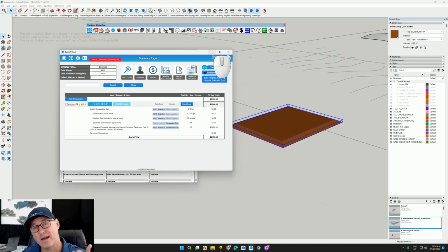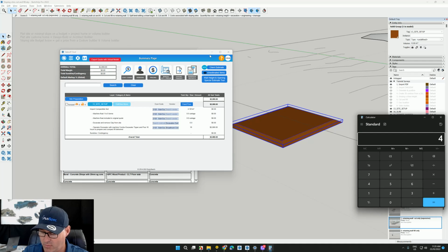Now, one thing about when you import fill, a truck would usually carry 10 cubic meters of soil. However, there is a lot of air inside of it, so usually if it's clay, it's 2.5 times the quantity, and so in this case it's 4.1 times 2.5. I would need 10 cubic meters of soil there, imported.